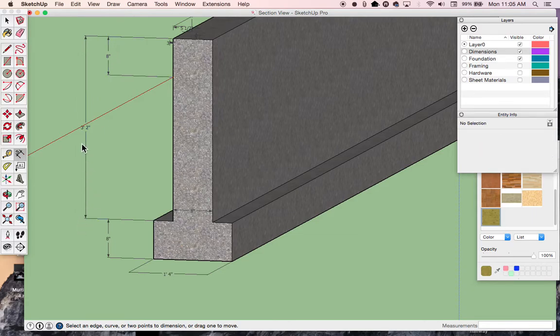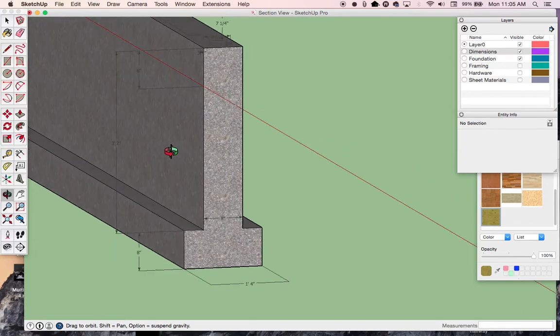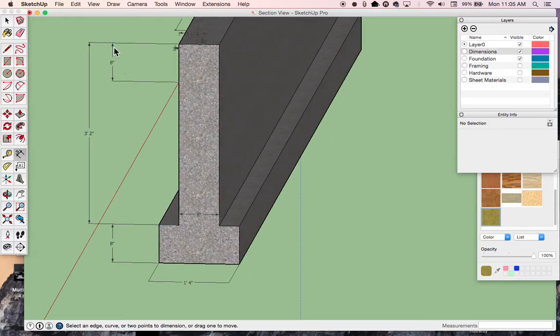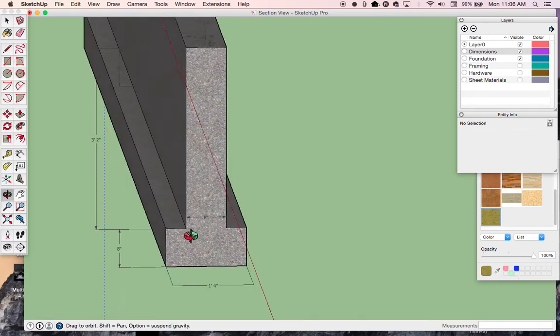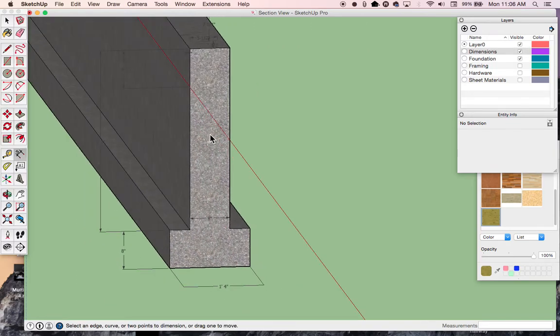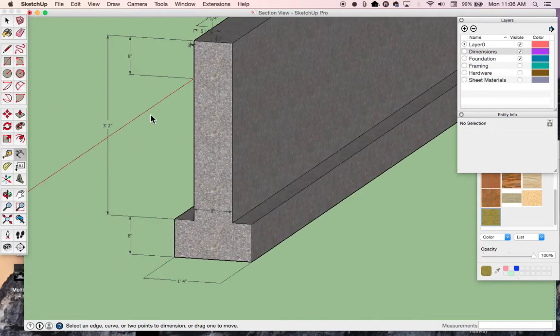That's allowing me to get up to the frost line, and then I'm leaving an additional 8 inches above the soil line. So the goal is to get this footer down below the frost line, which will keep, if this ground never freezes, it'll never push up or down. The house will not settle the way it would if you were to put it up above where the ground freezes. That freeze thaw will cause your building to lift or to fall, and that's not a good thing.